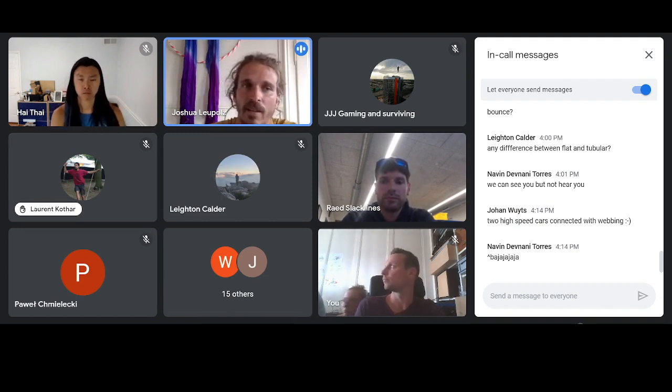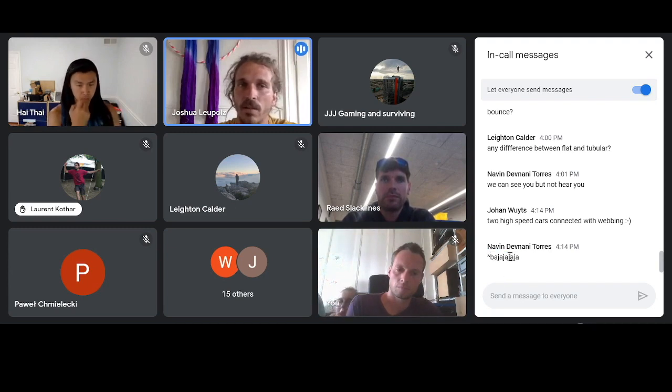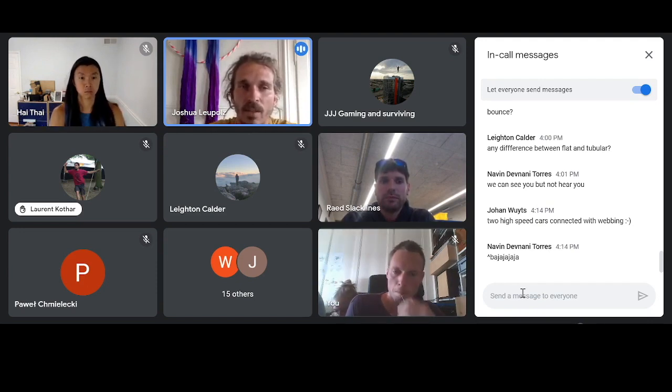Then you can also have a range again and say, okay, as long as you're between 4 and 5.5 at the peak, you can just compare the bottom to the top, have the difference in kilonewton there, the difference in stretch there, and then you get a percentage per kilonewton stretch value for this range. I guess we all agree that the most interesting part for us is between 2 and 5 kilonewton, because that's what you're trick bouncing on. That's why your leash falls normally happen there.